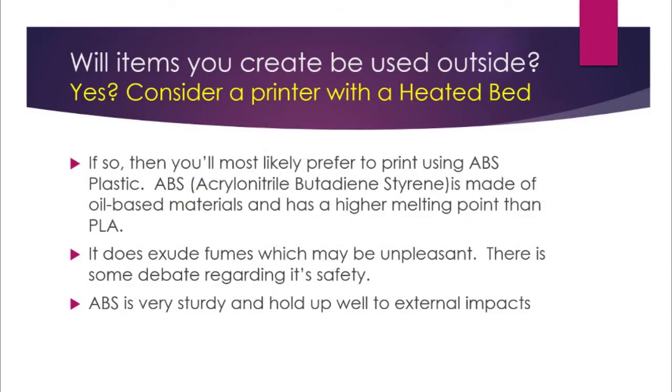First, will the items you create be used outside? If yes, you want to consider a printer with a heated bed. That is, ABS is the plastic that you're going to want to use. It's made of an oil-based material, and it has a higher melting point than PLA. If you're going to be using the object that you create in a hot car, for instance, or outside in the direct sunlight, ABS is certainly a much more reliable material for outside use than PLA.